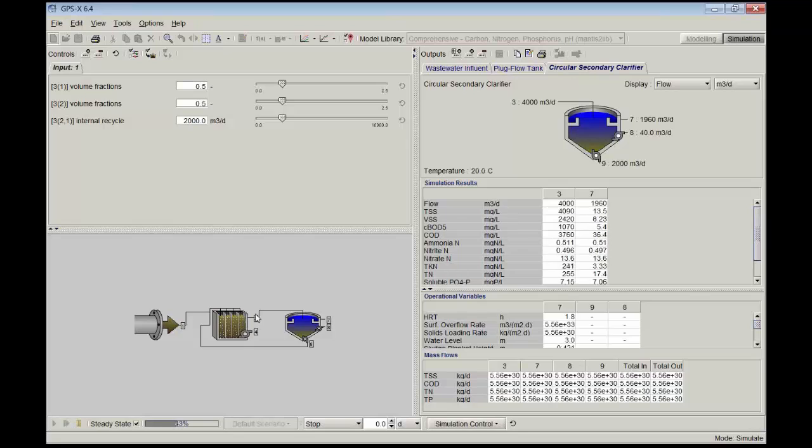Well, I'm just going to run it once at all of the settings that we currently have here. And so what we're going to see is, right now I'm looking at the clarifier. This column here is actually the effluent from that clarifier. And we can see that, for example, our ammonia is 0.7, and the TKN, or pardon me, total nitrogen coming out the back end of the tank is 17.1. So we're getting lots of nitrification, and we're getting probably some denitrification there, actually a fair bit. Remember, it was 50 for TKN going in. So we're getting, obviously, both nitrification and denitrification, but now the model allows us to play around with some of this input to try and improve things a little bit.